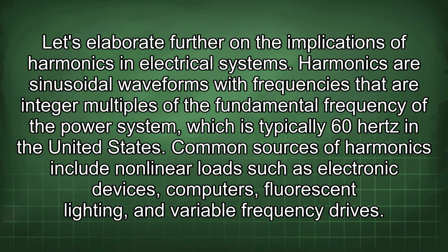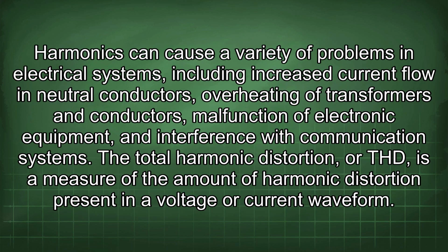Common sources of harmonics include nonlinear loads such as electronic devices, computers, fluorescent lighting, and variable frequency drives. Harmonics can cause a variety of problems in electrical systems, including increased current flow in neutral conductors, overheating of transformers and conductors, malfunction of electronic equipment, and interference with communication systems.